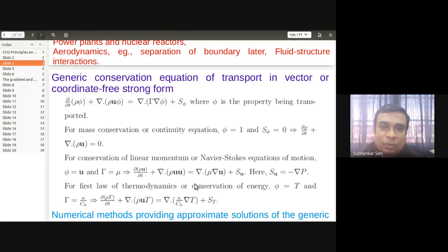Now, when we are using CFD, we modify this continuum or exact equation, and it is converted to an approximate equation. Since we approximate the equation, we also approximate the boundary conditions, initial conditions, and the governing computational domain. Because of that, the solutions we generate after solving this problem also become approximate solutions, but of high accuracy.